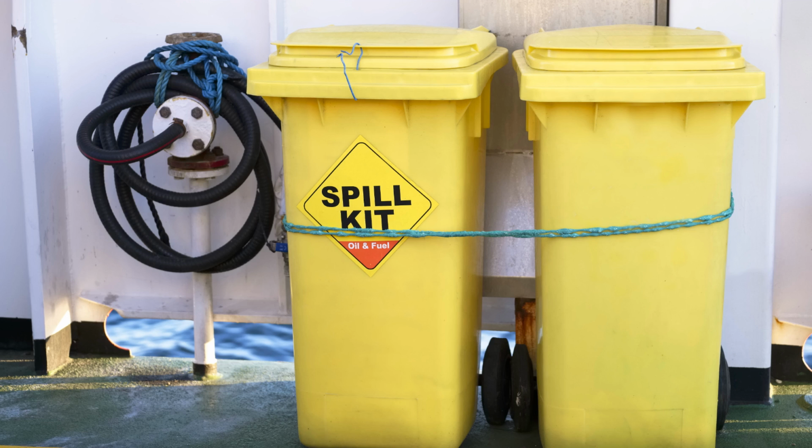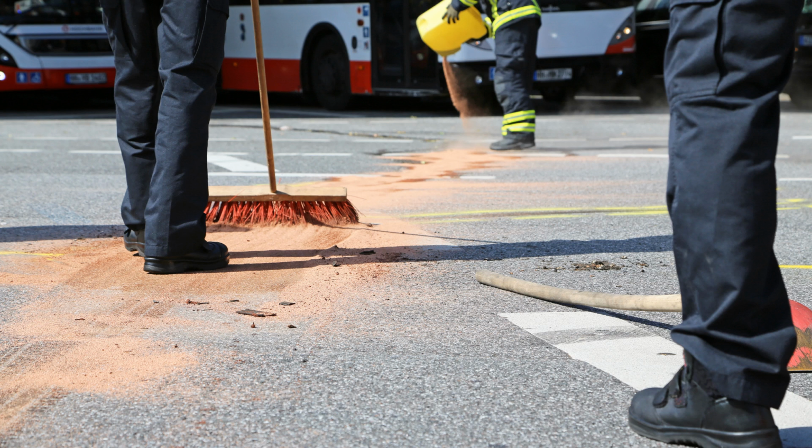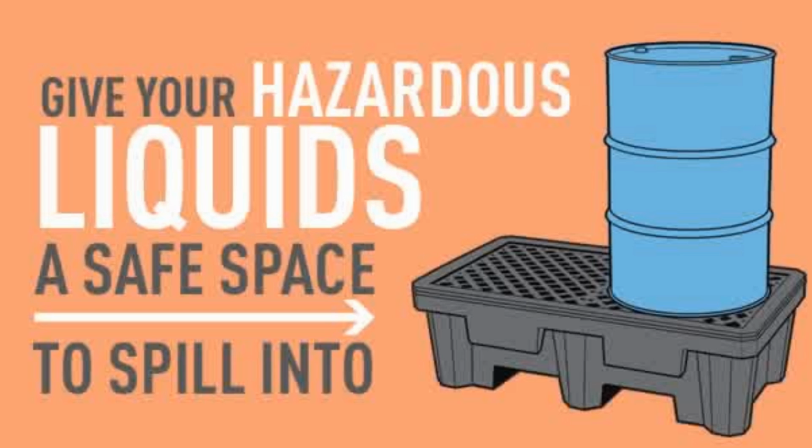Drain fluids as soon as possible from any wrecked vehicles. Keep spill cleanup materials readily available in chemical storage areas. Containers should be closed except when adding or removing chemicals. Use drip boards along tanks and faucets. And use secondary containment around oil and chemical storage. Secondary containment includes a wide variety of systems depending on your needs. If you don't have permanent secondary containment infrastructure, containment tools should be kept near storage areas and while working off-site.